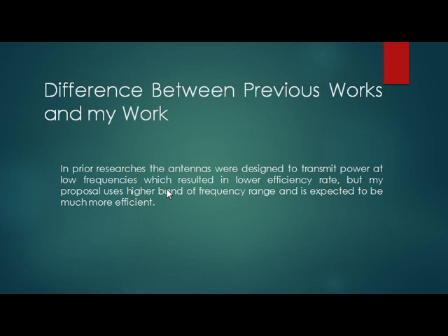The previous researchers used very low frequency, but I choose to use higher frequencies, because at high frequency the gain and directivity of the transmitting antenna increases, and also the power required for the transmission becomes low.